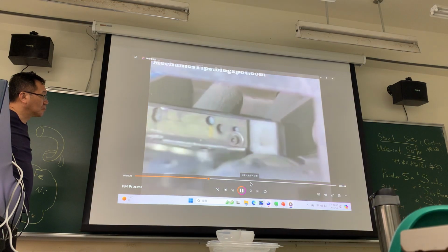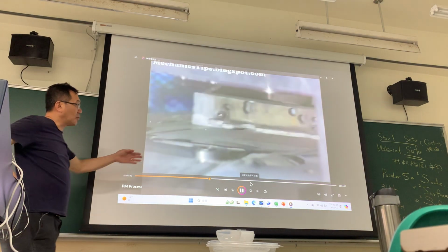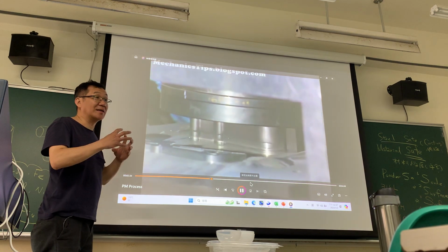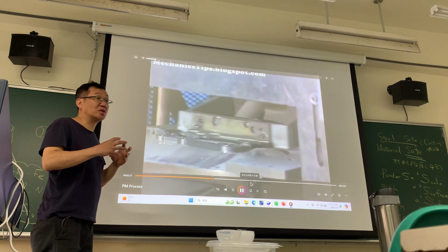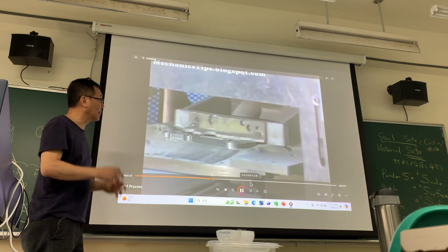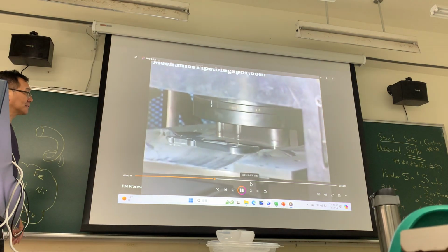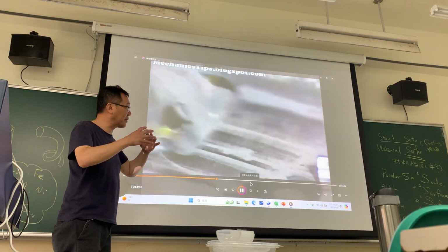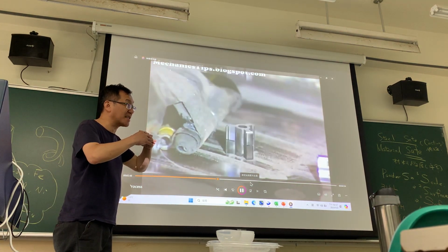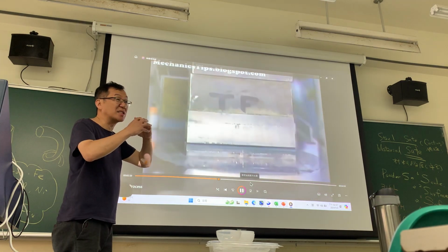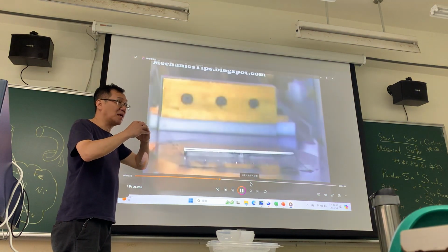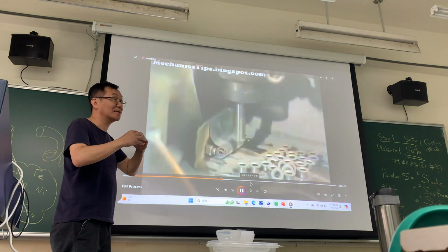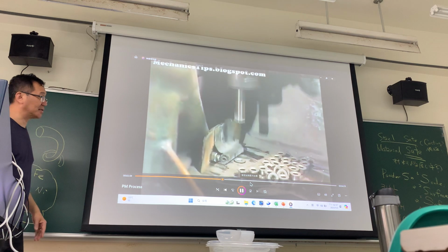In mechanical pressing, the powder is compacted. Okay, always we just watch after pressing. The parts should look like solid, but the strength is no good. It shouldn't be sintered. Pressures of 10 to 60 tons per square inch are created. But in the PM process, the green part goes to sintering. The shrinkage rate is very small, maybe not shrinking, just only the same size. So this is PM, different from MIM.